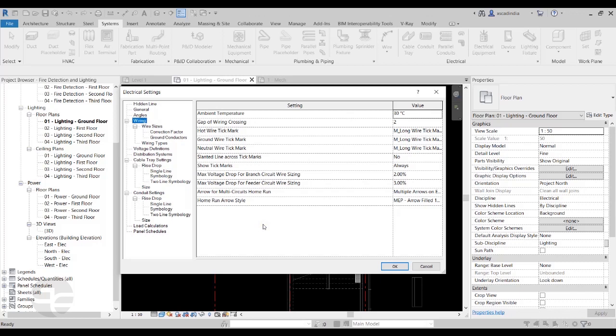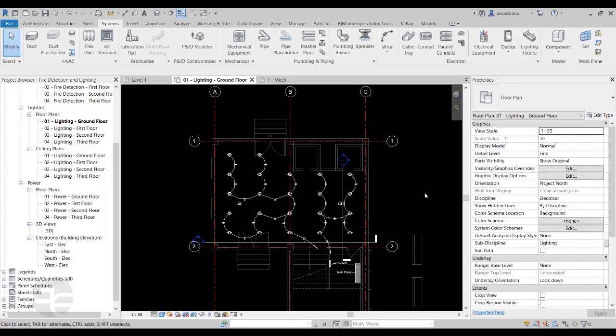The next enhancement that we are going to learn is to model the connection of panels through feed through lugs. In some situations, the electrical design requires a panel to be feed through lugs type. This situation can now be modeled in Revit. So let's see this in practical.